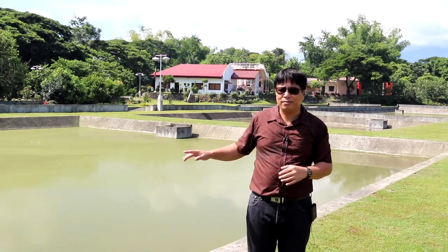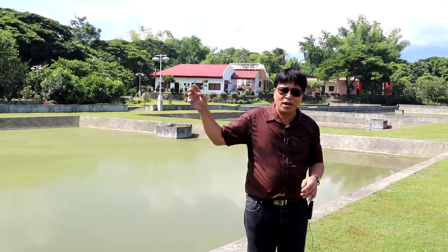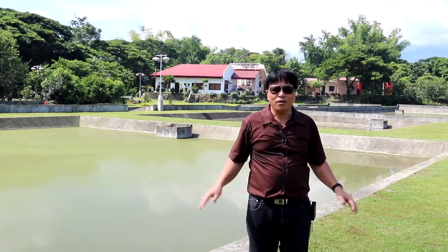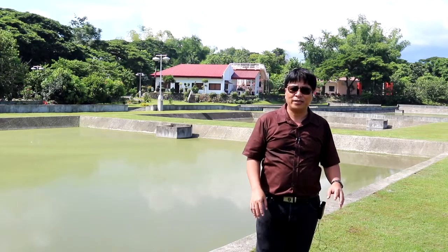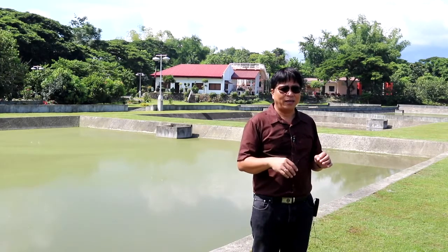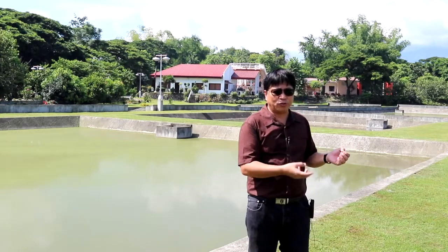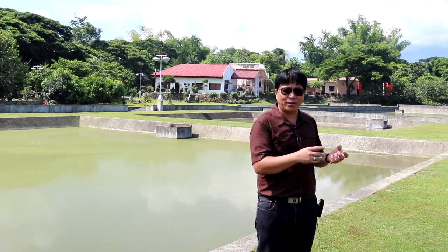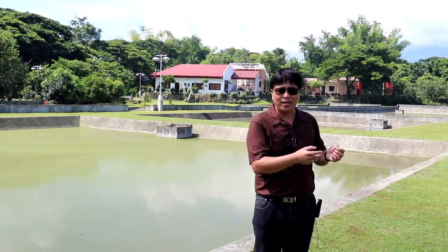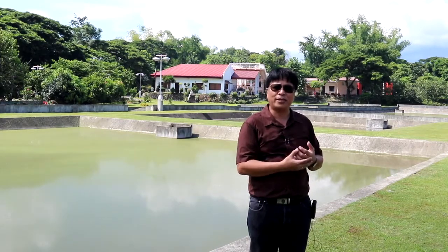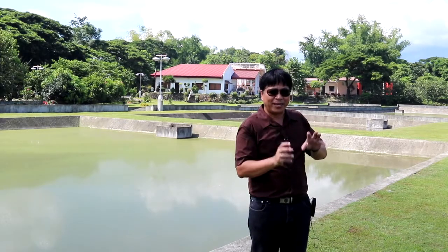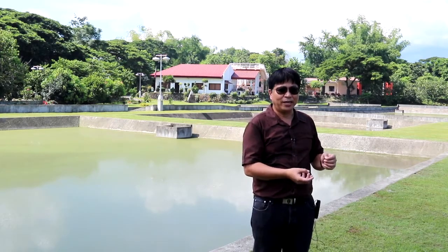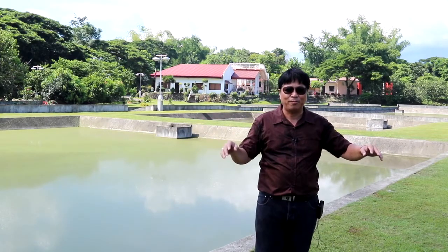In the anaerobic pond, we don't allow much sunlight to get in, while in the facultative pond, we allow much of the sunlight so that the algae, through a symbiotic relationship with the bacteria that digest the organics and the carbon dioxide, get to produce oxygen through photosynthetic action, while the bacteria down beneath need the oxygen, and they get to multiply and do the stabilization.